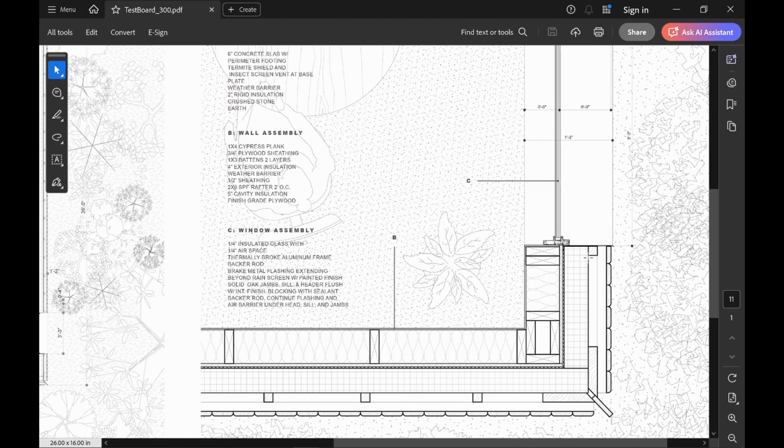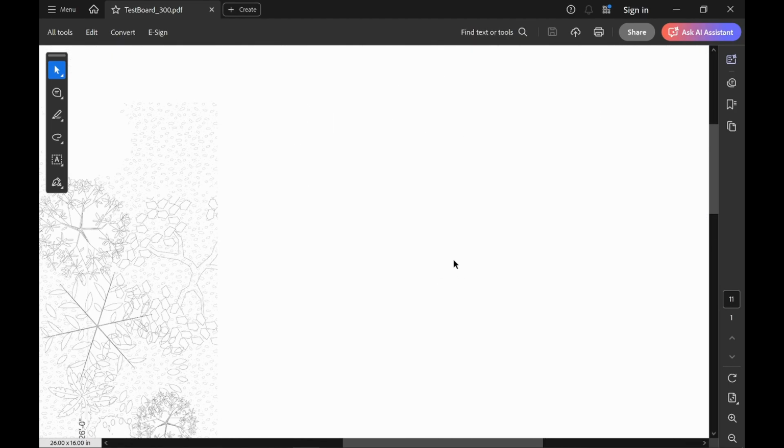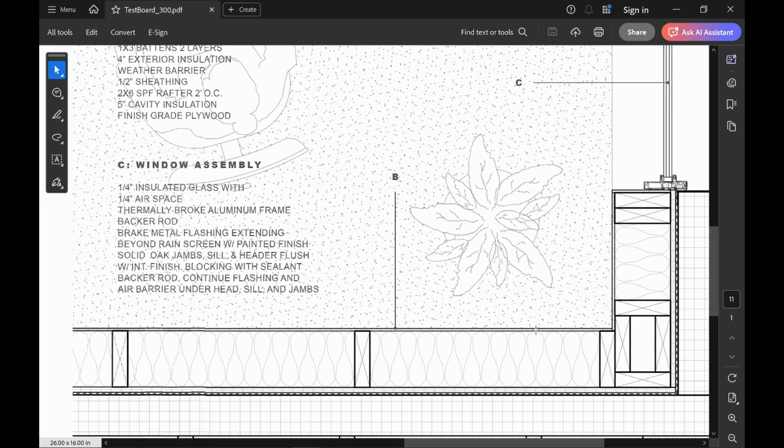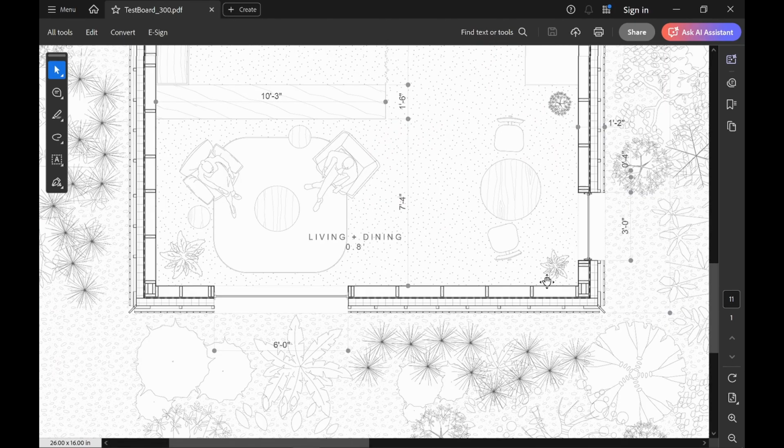And you're seeing a lot of detail here. You're seeing the different assembly systems of the facade and the battens and the rigid insulation and the membrane and the sheathing and the cavity with the framing and then the interior finish. Even on the window frame, if I zoom in even more, I'm at 125% right now, it reads very well. Annotations look great. I could label the annotations like 3-foot-inch daylight opening, 4-inch facade finish width, so you can do more labels to help with the annotations for graphic layout. But this looks great, and obviously this is what we did last time, and it looks fantastic zoomed in as well.